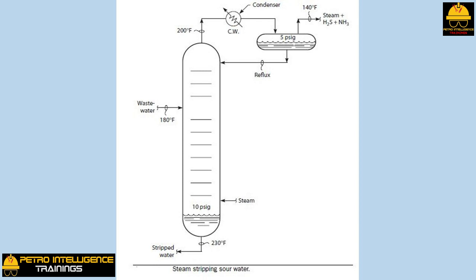2. A portion of the stripping steam is used to break the chemical bond between the water and the H2S and NH3 in the wastewater. When these gases first dissolved in the water, heat was evolved or released. This is called the heat of solution. When these same gases are driven out of the wastewater with the stripping steam, this same heat of solution has to be supplied. Again, this heat comes from condensing the stripping steam in the water flowing across the trays in the tower.